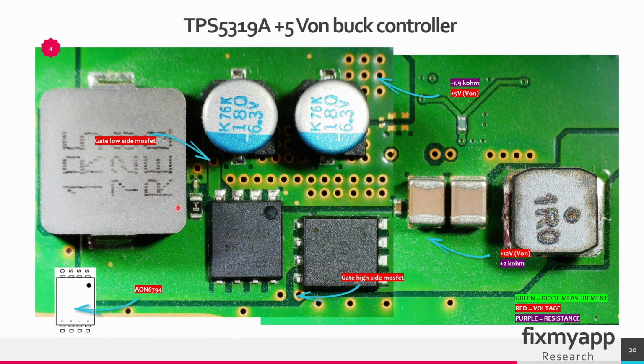Near the two MOSFETs we have the inductor. It's a large coil or a component labeled with an inductance value, so this is the inductance value. You can find this inductor between the MOSFETs and the output capacitors. The input capacitors filter the input voltage to provide a stable supply to the circuit. The output capacitors will smooth the output voltage by filtering out the switching noise.